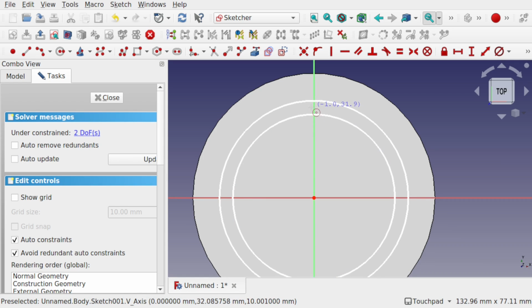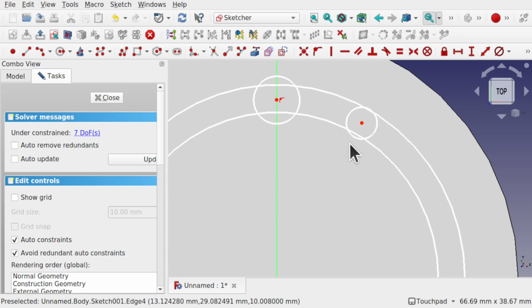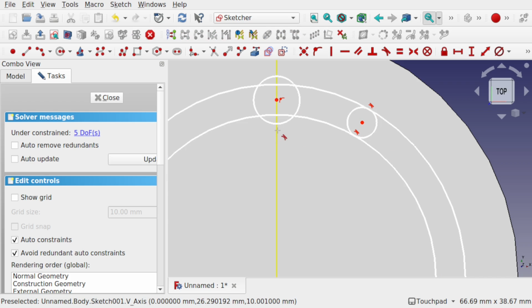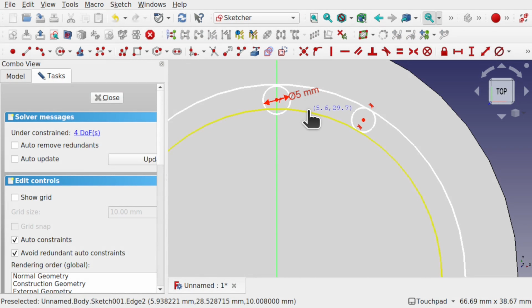Let's create another circle. I'm going to attach it to this line, and also I'm going to create another circle inside here. So we've got these here. I'm going to make this circle tangent to these 2 lines here. So I'm going to use the tangency. Make sure nothing's selected, use the tangency, and take this circle and this one and this circle and this one. So that's tangent now. Now we want to keep this one, which will be the screw head.